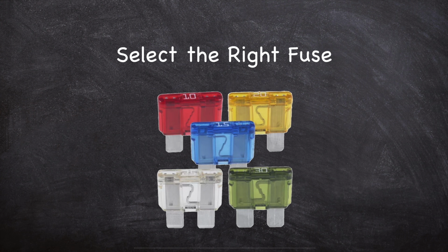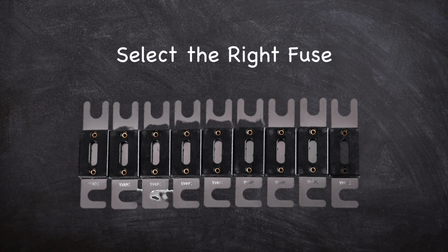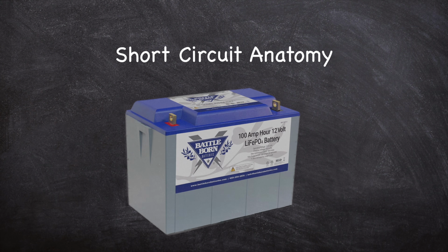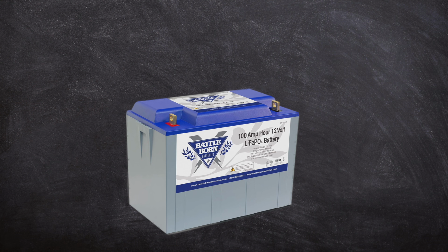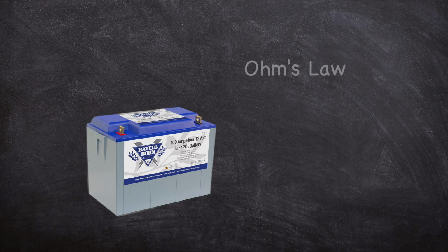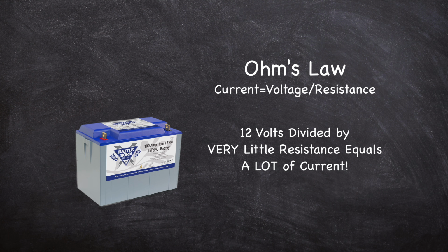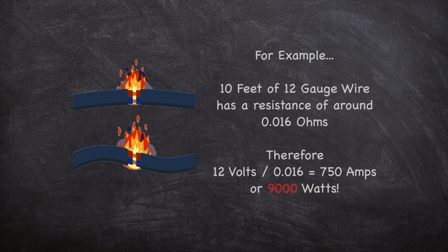Fuses are used to protect wires in the event of a short circuit. To understand what happens during a short, start with the battery, the source of power. During a short circuit, a vast amount of current will instantly begin flowing into your system. This current may be many times the rated output of your battery, possibly thousands of amps. Any wire that cannot carry that current will heat up and can catch fire. There are several things you can do to prevent this.